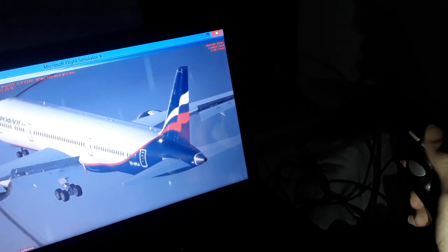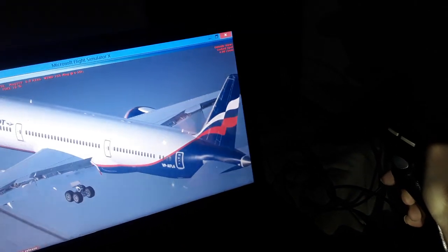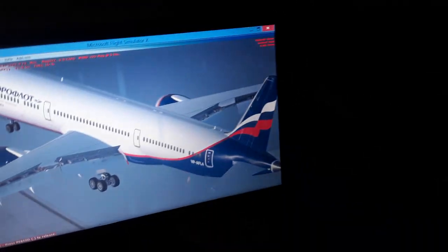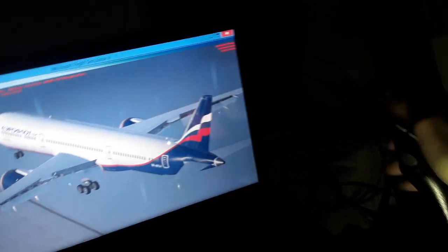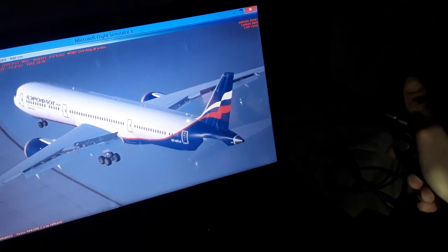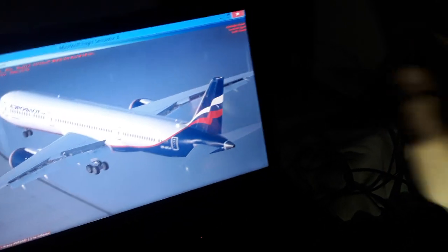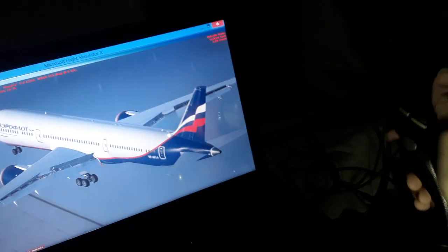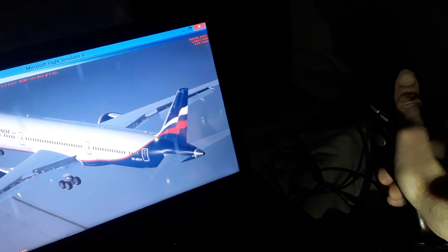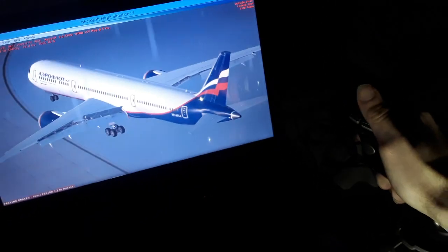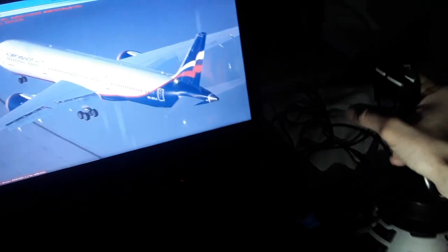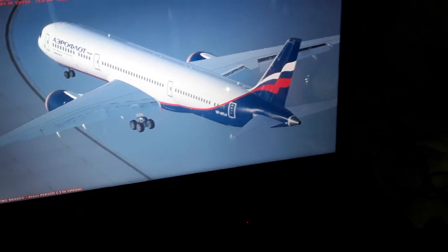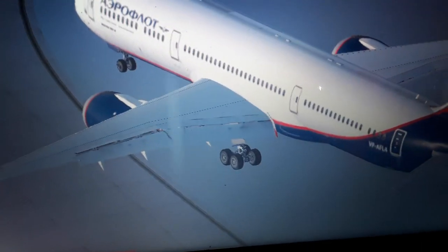So you can see we can use the elevator that traverses the lateral axis, the pitch axis of the aircraft, for climb and descent from wingtip to wingtip. You can climb and you can descend. We have the yawing axis, the vertical axis, for making yawing turns left and right, and also we have the rolling axis for making turns left and right like this, left turn and right turn, using the ailerons and the spoilers on the left and right wing and the flaperons, as you can see.